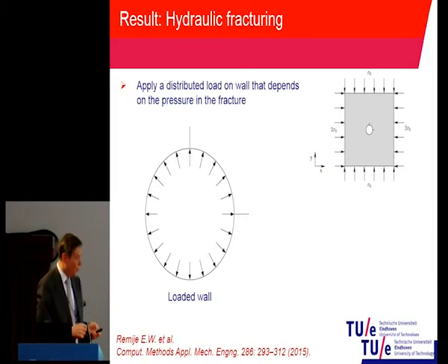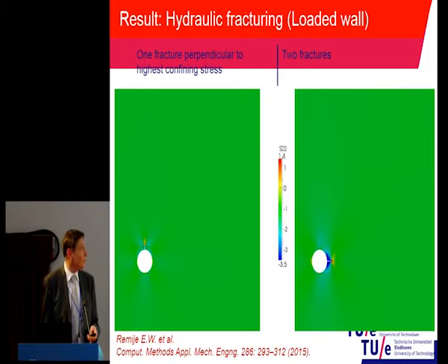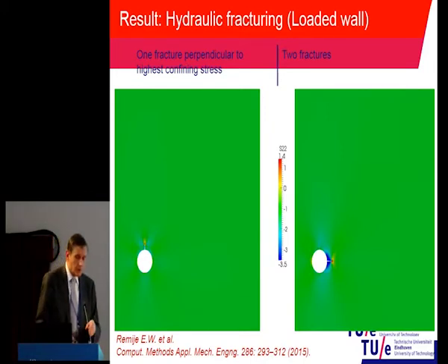We also did a crack propagation within a swelling medium, and here a very simple configuration, but we changed the external salt concentration. We could actually show that the crack propagates just based on a change in salt concentration. And these are further pictures of the same thing.